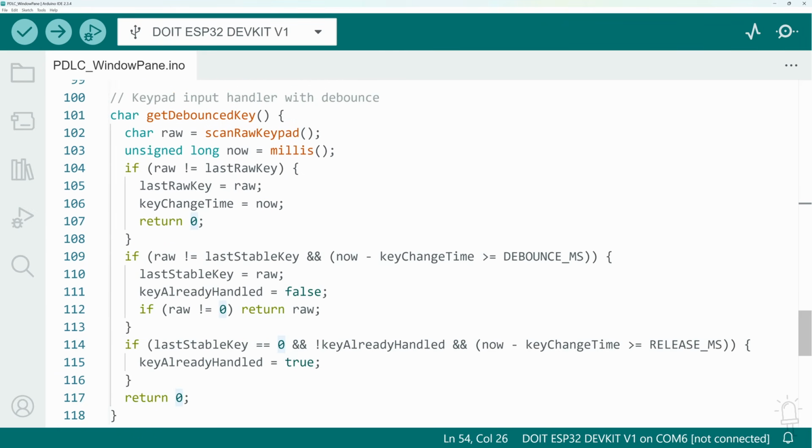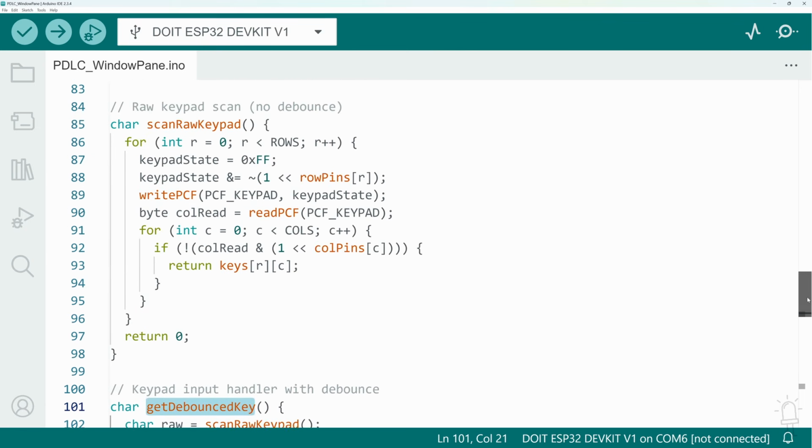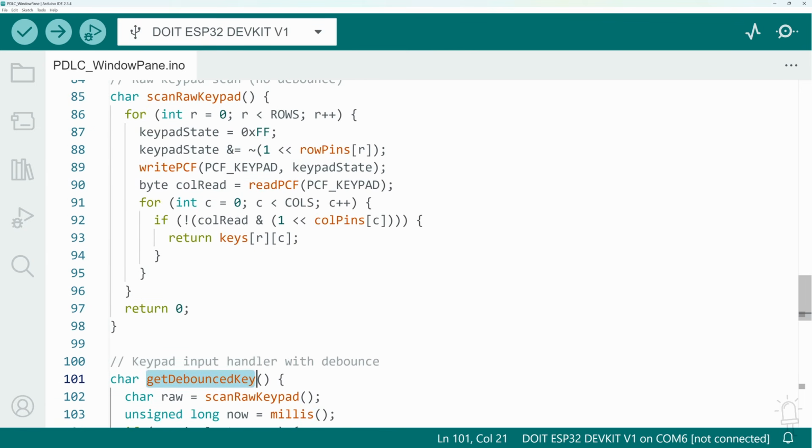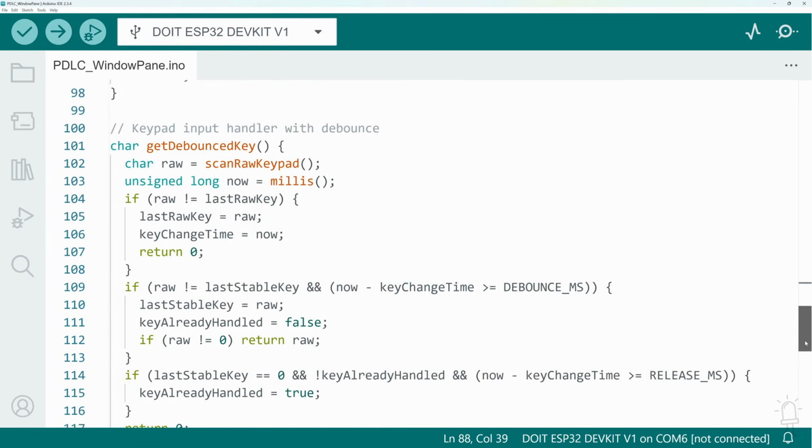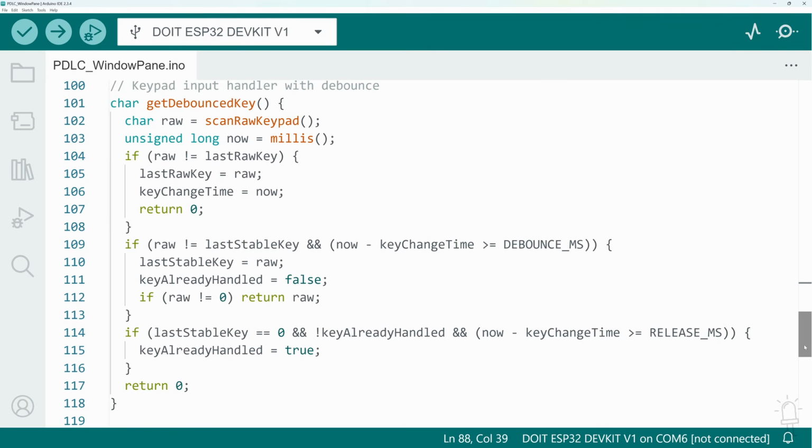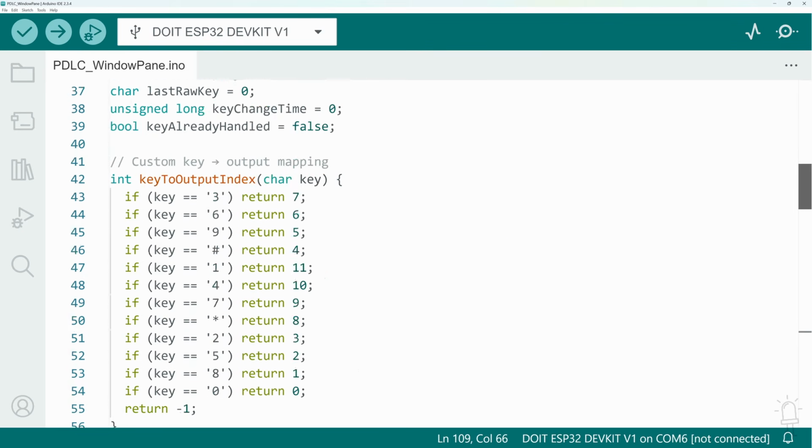And I added a debounce function to that. So this is the raw input. This just reads the value directly from the input from the I2C interface, but we actually want to get a little bit of debouncing on that to make sure, like I say, we don't accidentally toggle on and off the film too quickly. So this is where I define a very, very simple debounce function.